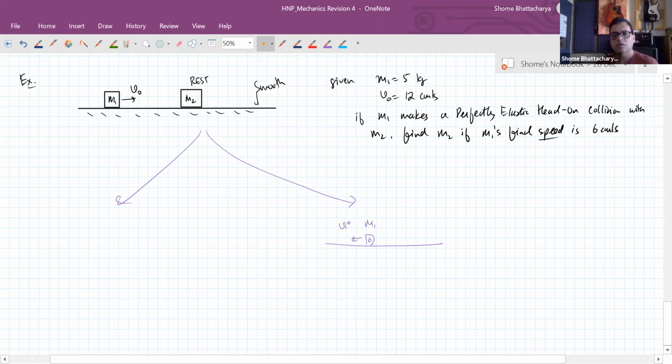One case is this, after impact, something like this, and one case is assuming that this is a heavier body, so it continues in the same direction. So if you take this case, you can just use the fact that e is equal to 1. That means v2 minus v naught by 2 has to be equal to v naught. Separation velocity is equal to approach velocity. So v2 has to be 3 by 2 v naught.